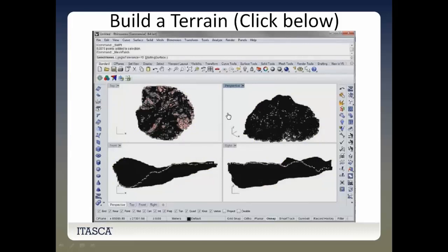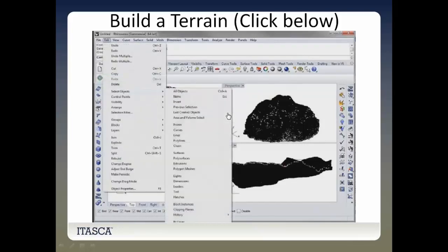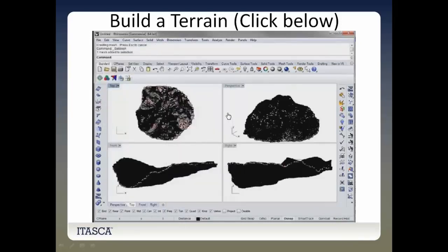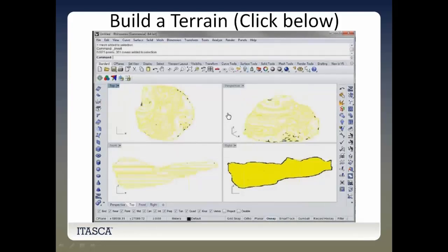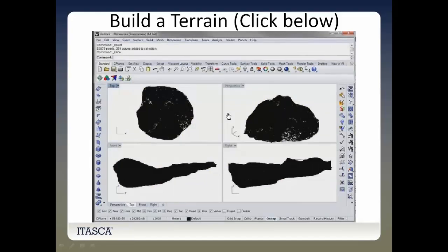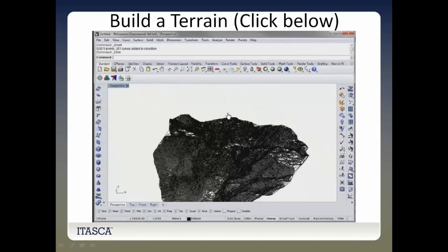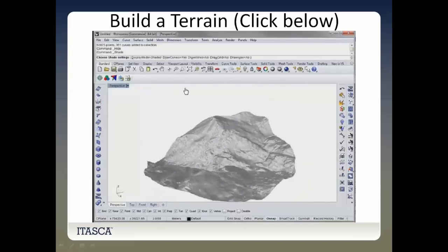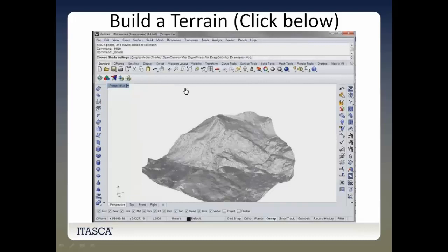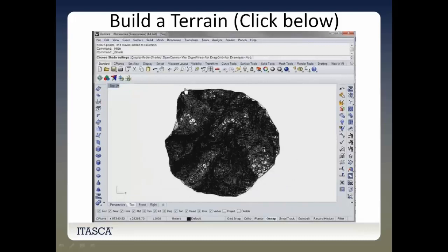You can generate a mesh from contours very easily, but here I'm generating points from these contours, and then I generate the mesh from the points. It's a much faster process within Rhino. So I use this tool within Rhino, which is a Delaunay triangulator. At this point, I hit my points, and I have now obtained a mesh using the Mesh Patch command, which produced a topography for me. This topography is way too busy. There's too much detail. It needs to be defeatured, and we don't need all of it.